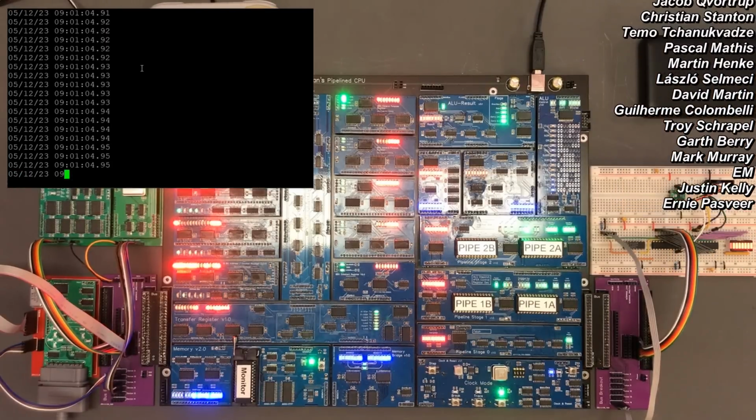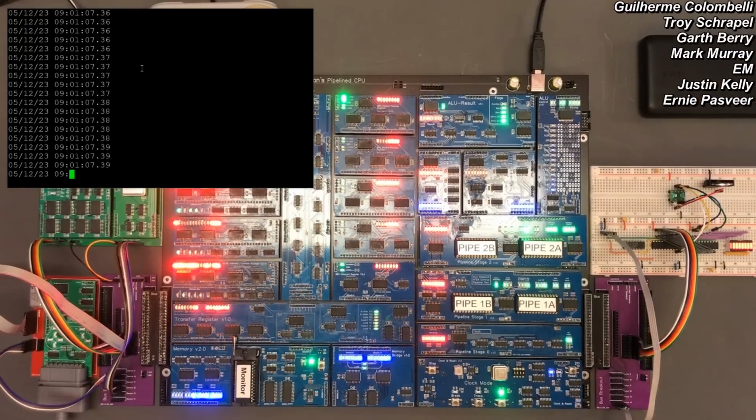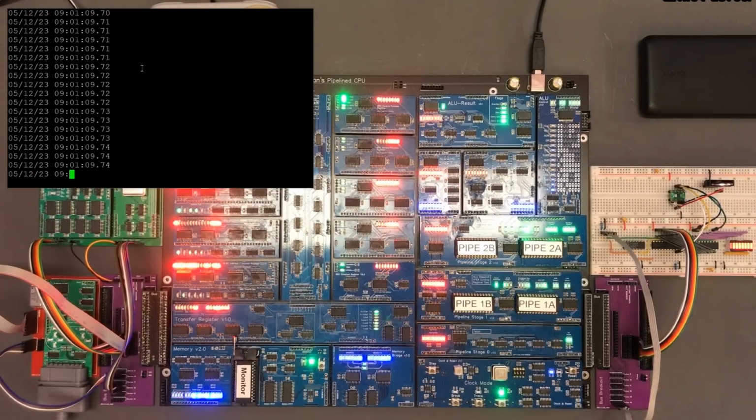I think what it would be good to do is write some slightly better code for setting the time that makes it easier to get it lined up exactly with another time source, but the battery's clearly allowing it to hold time. I really like the idea of having a clock source and a backup battery that will allow it to display the current time on startup, but we've also got a reliable hundredths of a second timer here, which will be handy to do things like timing length of execution if we write a few library functions. It's not terribly high precision, but it's obviously a lot better than trying to manually time things externally.